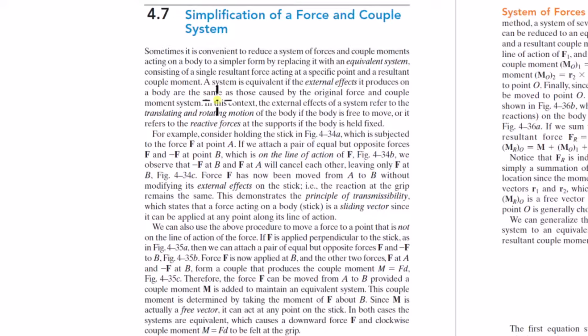This is the idea. No matter where you place that force along its line of action, when you do the static analysis and solve for the forces at the supports, or in dynamics solve for the resulting acceleration or motion, you're going to get the same reaction forces and the same motion. The external effects it produces on the body are the same. In this context, the external effects of a system refer to the translating and rotating motion of the body if the body is free to move, or to the reactive forces at the supports if the body is held fixed. That's the idea.